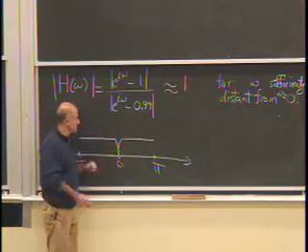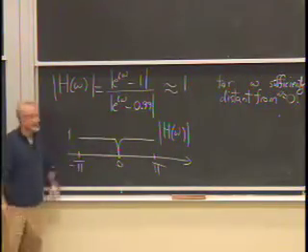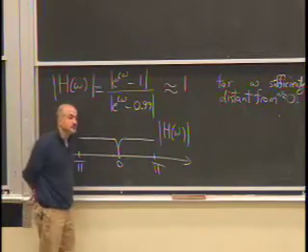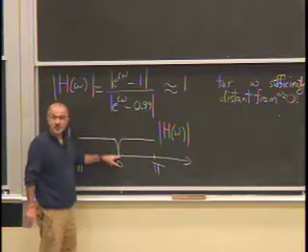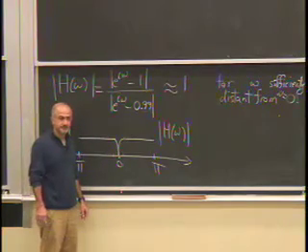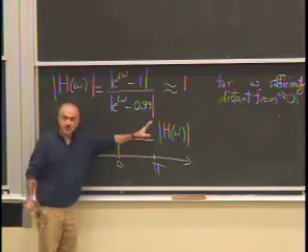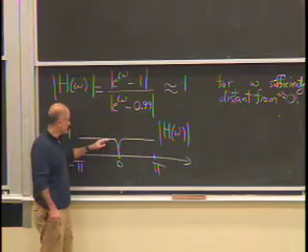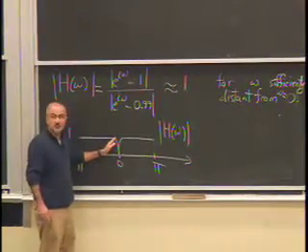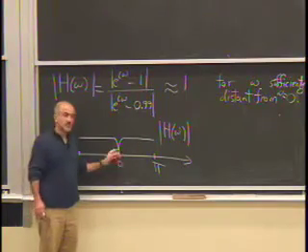Well, yeah, the magnitude response will look like a notch in the middle, but what is it doing to the signals? It kills the signal that's been notched and passes everything else, as an equal opportunity filter. Okay? Doesn't care about what the others are. In terms of magnitude, the phase will invariably be different for different frequencies. But in terms of the magnitude, the amplification that it sends each of these frequencies, it doesn't care where you are in the spectrum as long as you're not 0 or a very tiny neighborhood around 0.